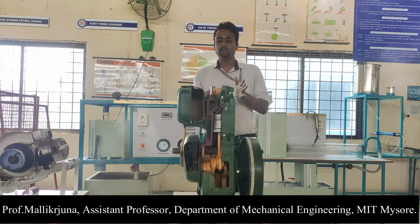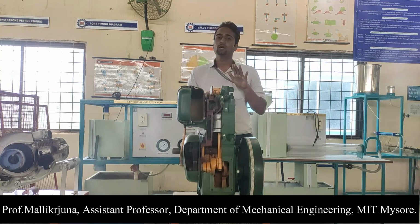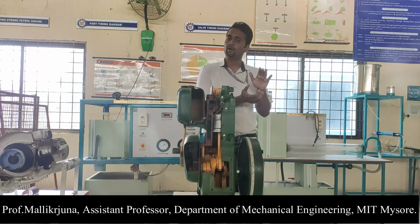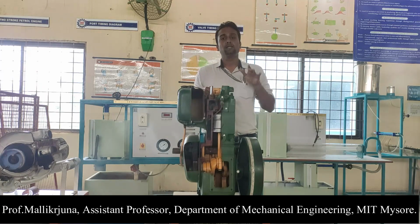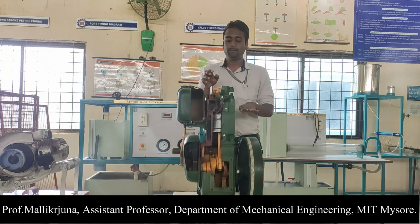Now what theory says is, during the suction stroke, the inlet valve is opened and the outlet valve, I mean the exhaust valve, is closed. During the suction stroke, the charge enters into the cylinder in case of a petrol engine, whereas in case of a diesel engine, only air enters into the cylinder till the piston reaches bottom dead center. Once the suction is completed, the compression stroke starts from the movement of the piston from BDC. During that time, both the valves are closed, I mean the inlet as well as the exhaust valves are closed.